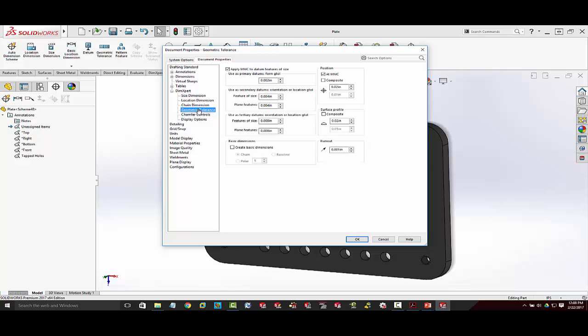For the GD&T specifically, do we want to use maximum material condition at the datums or at the position? And what should the primary, secondary, and tertiary tolerances be? Those can all be defined in this template.